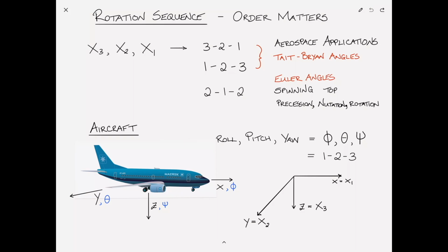This is a problem that we don't generally find in a time-stepping solution because as long as your time steps are small enough, it's unlikely for most situations that you'll be dealing with that your object is going to rotate by 90 degrees between two successive time steps. However, if you're comparing the orientation of the object to an inertial reference frame, then certainly gimbal lock is something you need to be aware of.